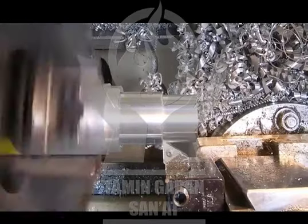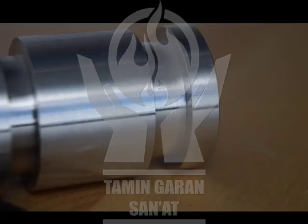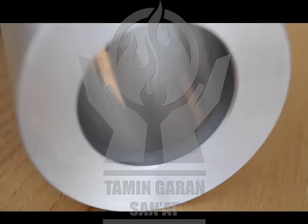Surface finish on the components is extremely important. As a general rule, the side of the gland and the bore or rod should have a 32 RMS surface finish for static seals. The wall of the gland can be slightly rougher at 64. This is where the piston seal really shines, since it's typically more difficult to verify the dimensions and finish on a rod seal gland.